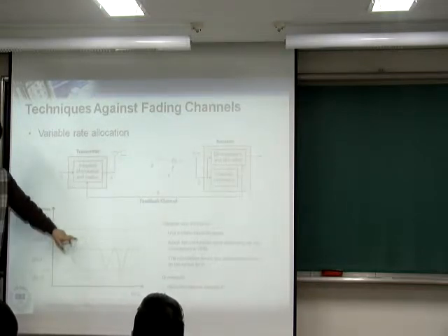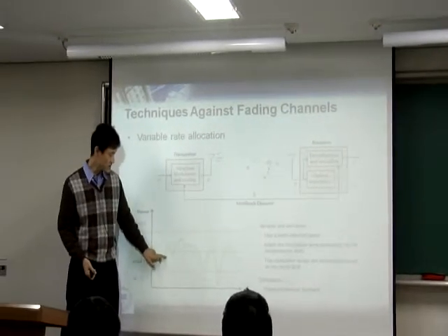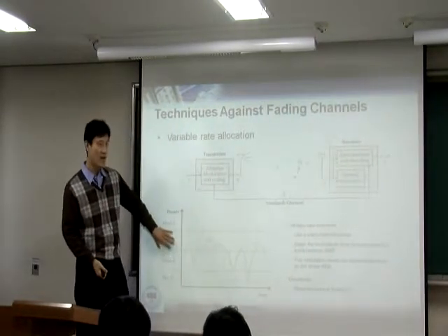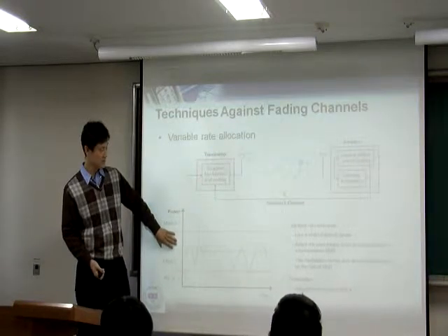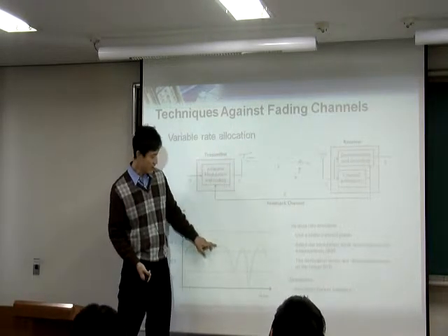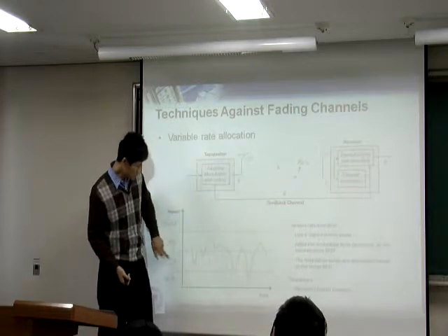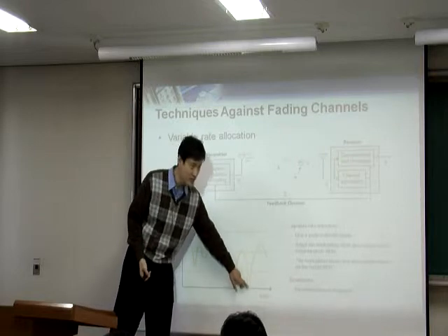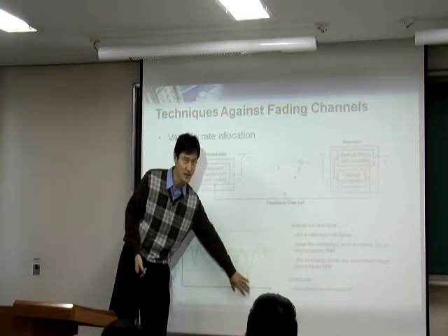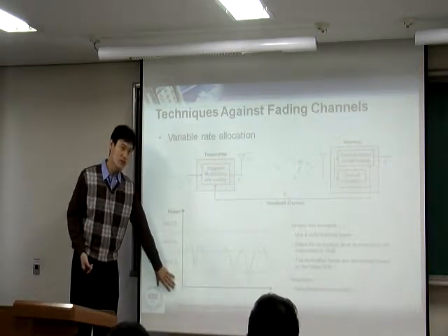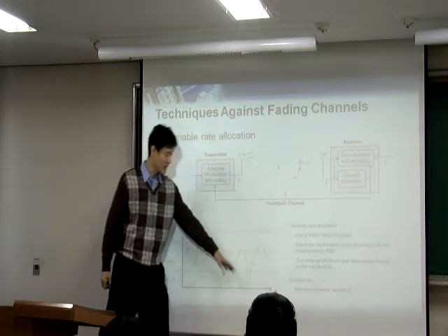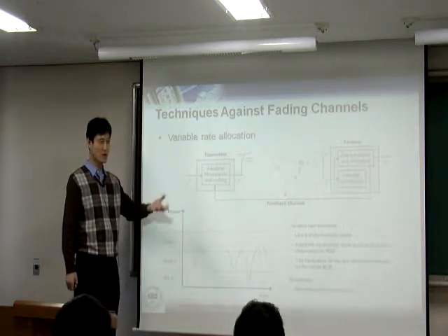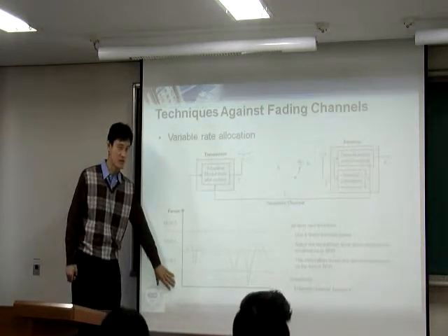But as time goes, my channel condition is a little bit improved. Now it's a little bit better. In that case, I'm going to use a little bit higher modulation. But sometimes you go that way and you go back to the lower modulation. Sometimes you go even further down, you are in deep fading. In that case, you may decide, okay, my channel is too bad. If I transmit something anyway, it'll be broken anyway. So let's not transmit.